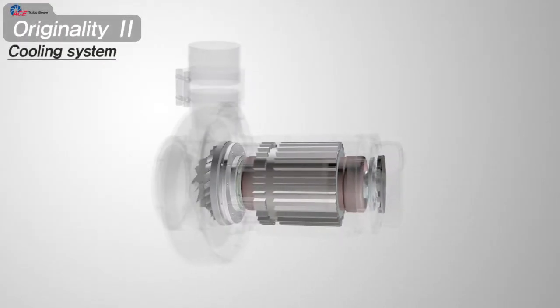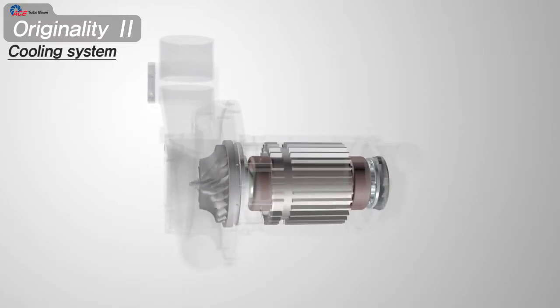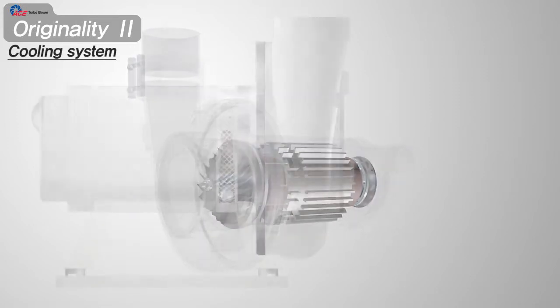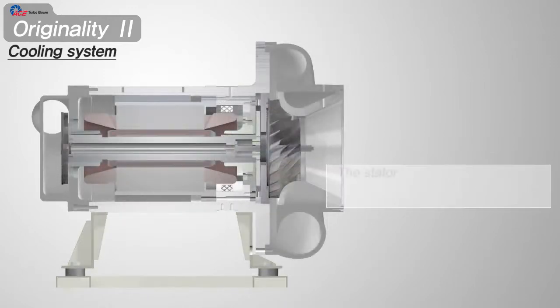The motor cooling system is the most important in the turbo blower because the high-speed motor has a small radiating surface for its heat source. Ace Turbo blower is cooling the stator and the rotor separately.